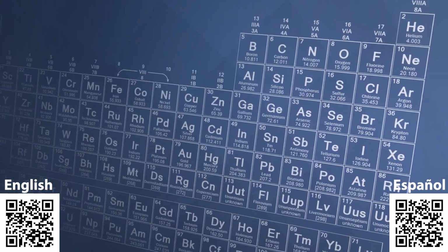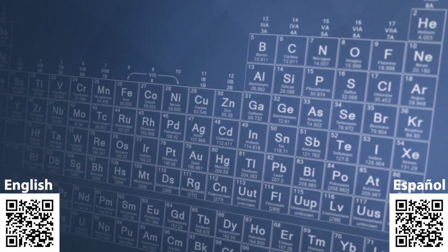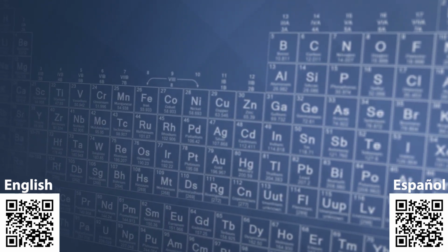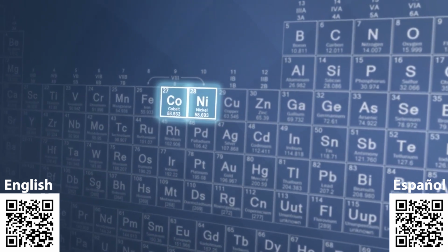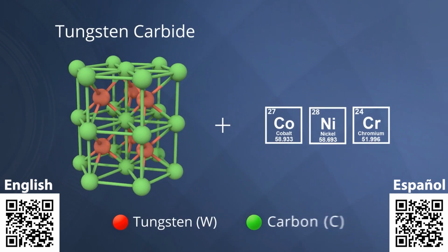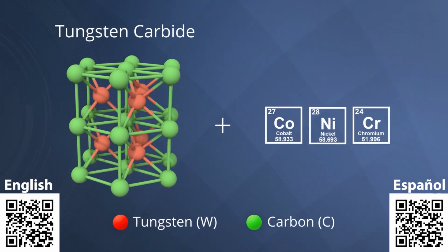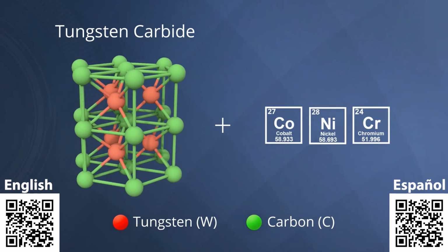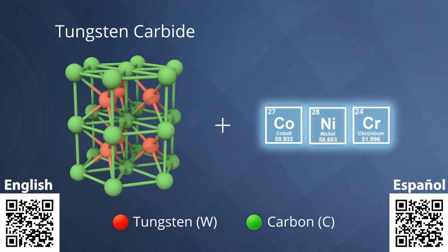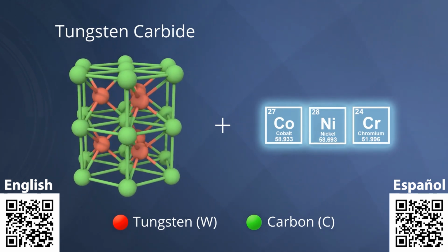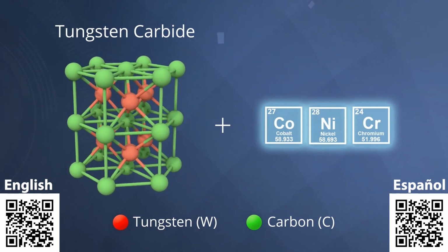Now let's discuss the role of trim material in resisting erosion. For a long time, choke manufacturers selected their trim material from a nickel or cobalt binder tungsten carbide. To address both corrosion and erosion, carbide vendors began using a composite binder, a mix of cobalt, nickel, and chromium in a tungsten matrix. This material is traditionally referred to as tungsten carbide.